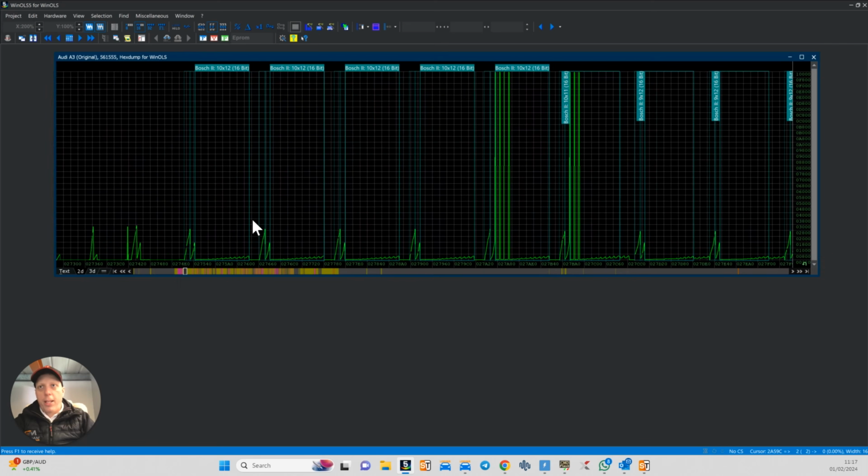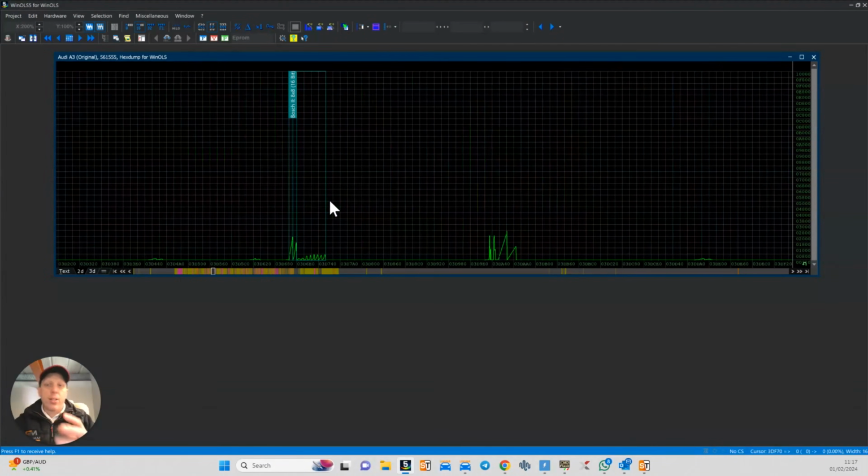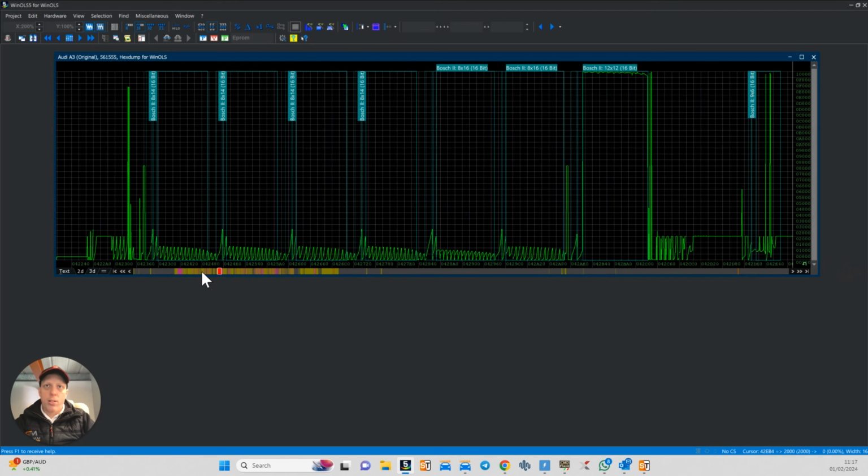So the biggest problem for everybody is the ECU's got, say, 10,000 maps in plus, each doing its own little thing within the software. So it's not just like, I want to raise the torque, where's the torque map? It's not, I want to change the boost, where's the boost map? It doesn't work like that. It does in a sense, but there's going to be other maps that affect that map. There's always a process between what you want to do with a car and how you've got to do that in the ECU to get it to work.